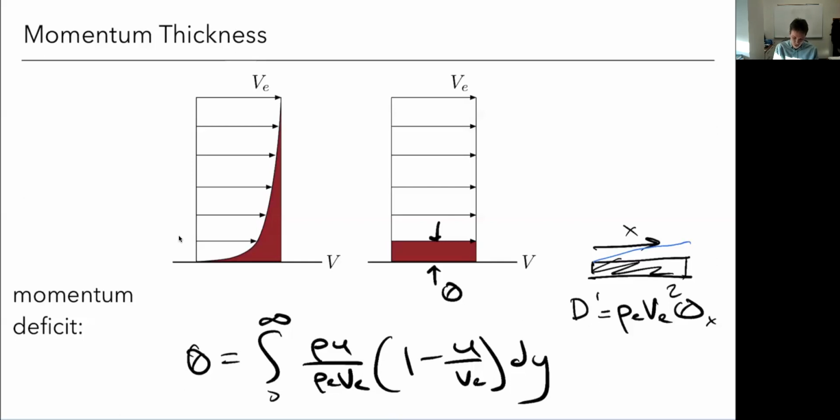And by the way, this is why, if we look at this expression, you'll note that the skin friction coefficient is highest when x is small, which is why, say for a hobby airplane, if we put tape or a smoothing agent, we put it towards the leading edge. Or if we were sanding, we put more focus towards the leading edge because that's where the skin friction coefficient is going to be highest. We get the most bang for our buck there, especially if we're adding weight through things like tape. We mainly do it towards the leading edge.